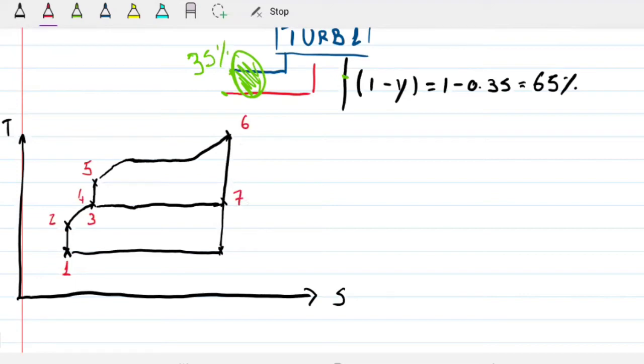And then on state 7 is where we have the split. Half of it, not half, 35% goes this way into the open feed water heater and the process heater. I'm not sure how much for each. And we know that the remainder, the 65%, goes down here to our 8. And then finally we have our 9, which is over here.